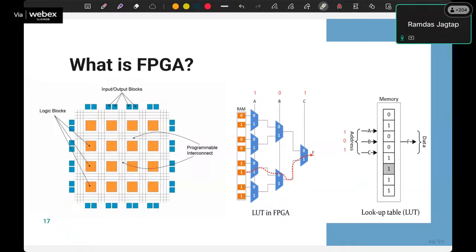That memory element we have represented in this tabular form, that is RAM, and we can configure, that is program, that particular location using HDLs. We can assign some values like zeros or ones. In digital, everything is zeros and ones. Once we program this memory, we can choose any output from this memory via the multiplexer.